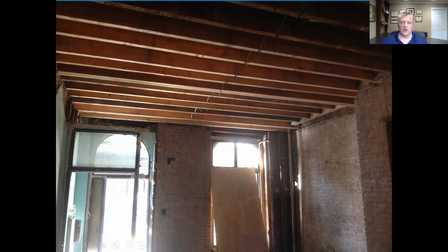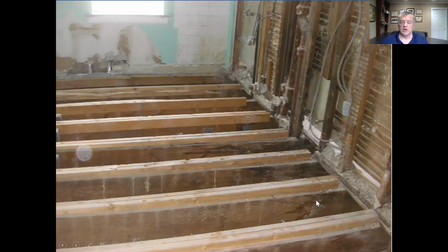Excellent. Starting to look like a building again. We're going to leave some of our joists. We're going to sister some of our joists, which means put one next to it. We're going to build up on some of our joists. Again, every job's different. Every area is different. We don't know until we remove things. And the architect and structural engineer will say, here's the best path forward. We made assumptions, but we just don't know until we get in there.